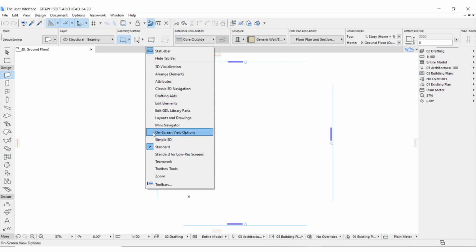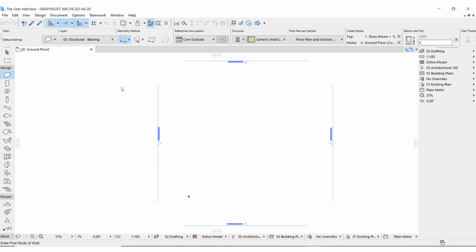Displaying toolbars. To display a toolbar, right-click the title bar of any toolbar on screen to display the list of defined toolbars. Click any toolbar in the list to display it. Or choose its name from Window, Toolbars.